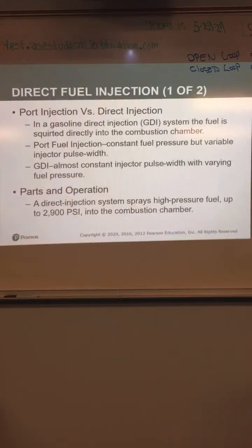Port fuel versus direct injection. Squirted directly in the combustion chamber. Constant pressure but variable injector pulse width. GDI is almost constant injector pulse width with varying fuel pressure.